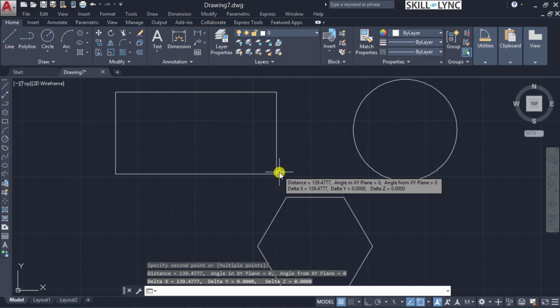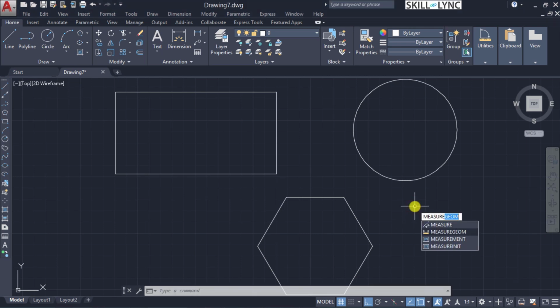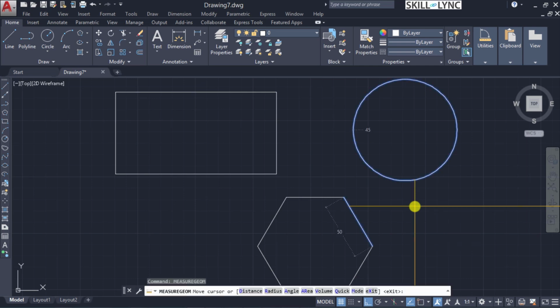So this means that you can use this distance command in different planes of reference also. So you get information within that same plane and also with the other plane modes. So like this we have different options to measure the different properties, that is the radius, angle, area or distance. So towards this we also have a group measure operation called the measure geometric property. So once you invoke this property, this is where you get a dynamic referencing of all the components that you want.